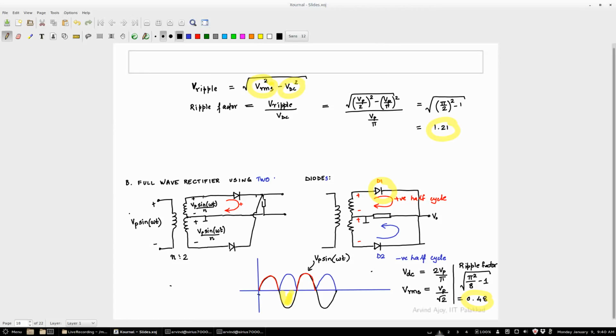Correct? Many of the devices will actually have a protection so that you can't. That is the most sophisticated version of these things. You take your laptop charger, even if you try to draw more current, it will just saturate at whatever current it's rated at. Or a little more, we'll see how to do that. So similarly for the diode, yes, you need to know how much current you're going to actually rate your diode to.